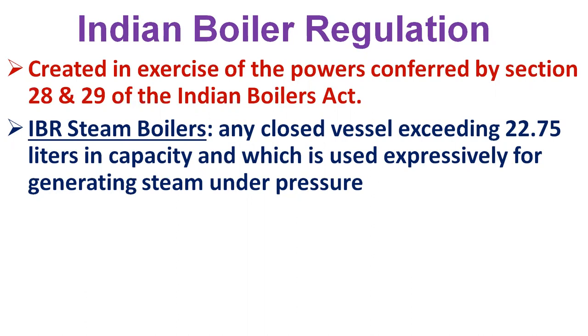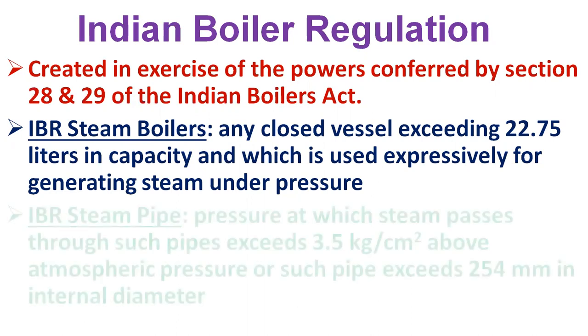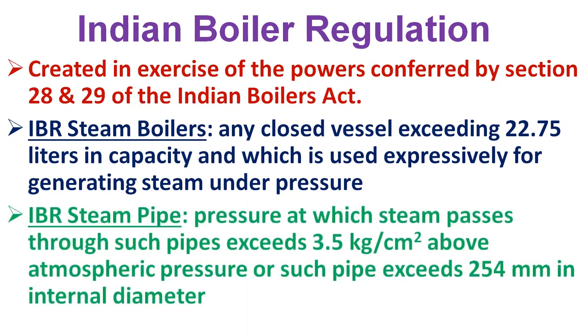An IBR steam boiler means any closed vessel exceeding 22.75 liters in capacity and which is used expressly for generating steam under pressure and includes any mounting or other fitting attached to such vessel, which is wholly or partly under pressure when the steam is shut off.